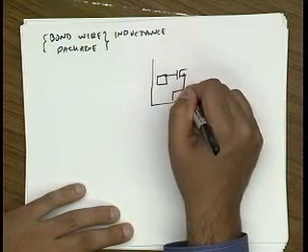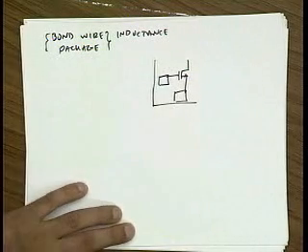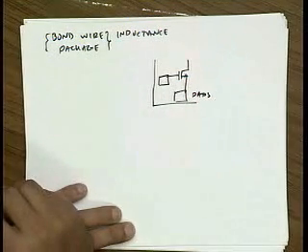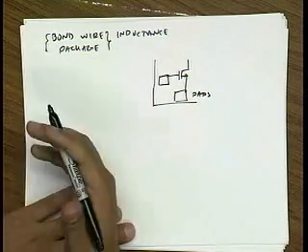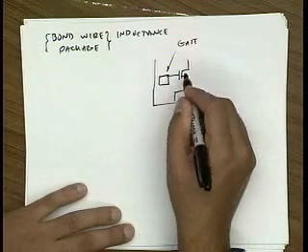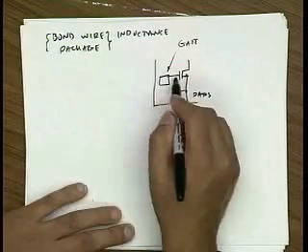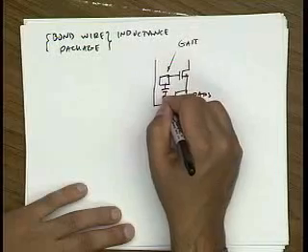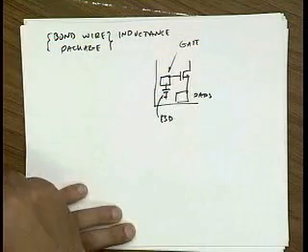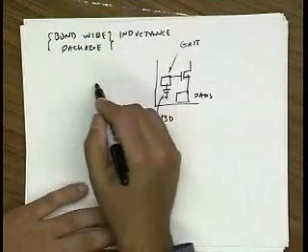So here's my transistor input stage. And I want to connect this to ground on this side and to the signal on this other side. But realistically, because these are pads, and these pads have to interface with the external world, especially here, this is a gate. This touches the gate. This is very electrostatic sensitive. A small voltage here can easily destroy this device. 10 volts will basically destroy this device. So I have to put ESD, a device for electrostatic discharge. If there's any static buildup on this node, it clamps it to ground and prevents it from going into this device. Okay?